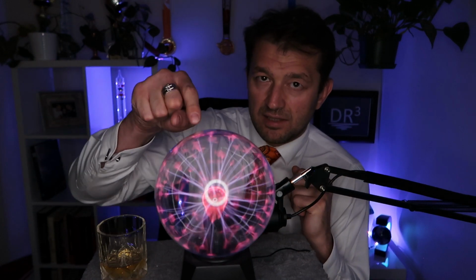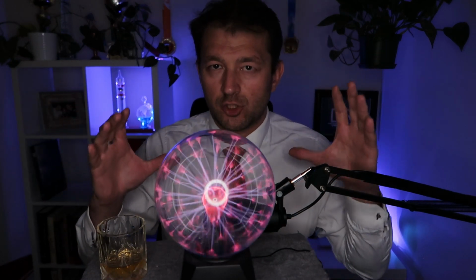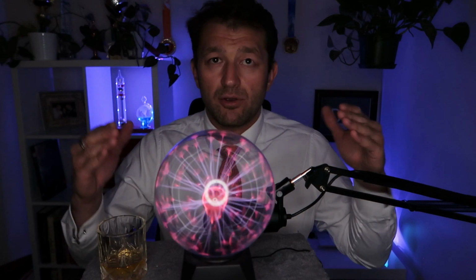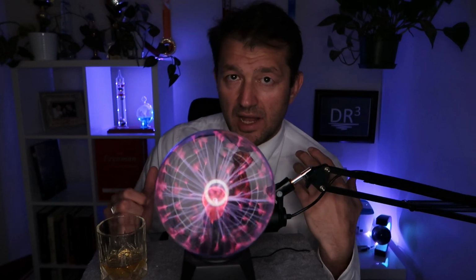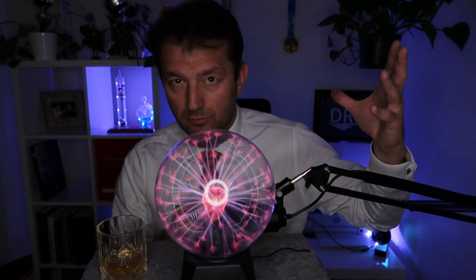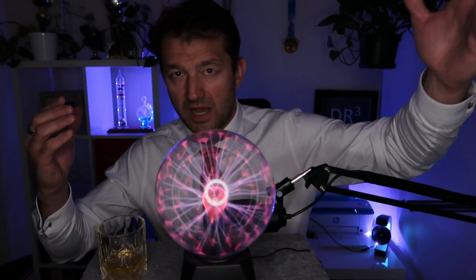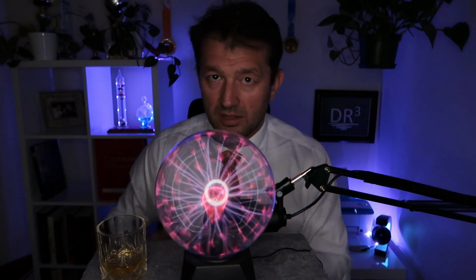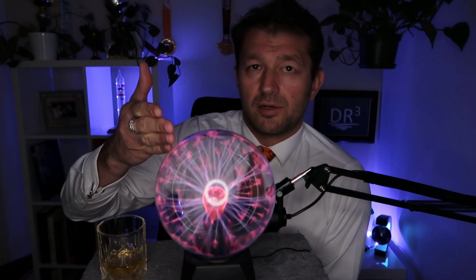And in this case, that energy is supplied by this high frequency current that is creating an electric field. This electric field is strong enough to ionize these atoms of noble gases. Ionize means the positive core is left without negatively charged electrons, and then you have positive ions and you have negative electrons that can conduct electricity, conduct current, which is happening here.